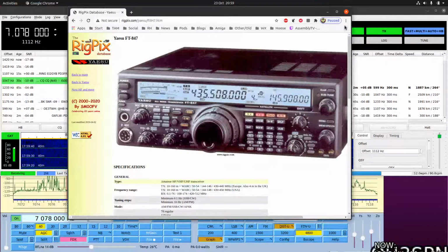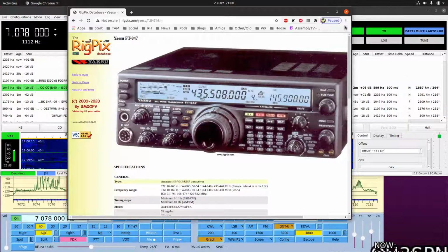With the AGC switched off, any strong station on the band, front end, goodbye. Distortion, noise, absolute clipping. Then I'm back to hitting the RF gain, and I'm dropping the RF gain down, and suddenly those stations that I was copying perfectly at minus 22 dB on JS8 are now no longer there. But I should shut up, because I am happy with the radio.